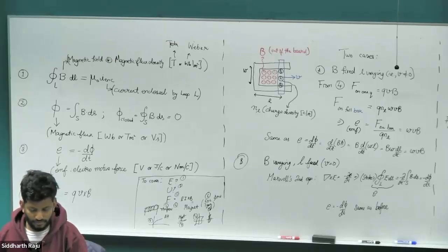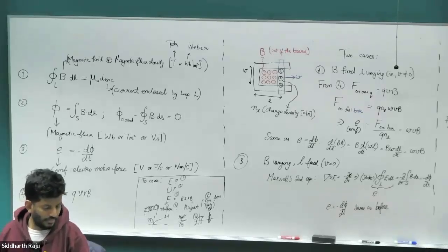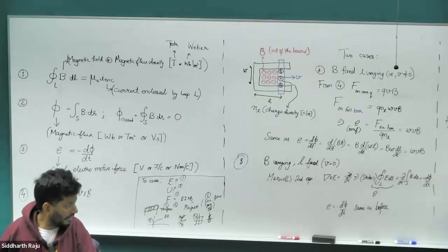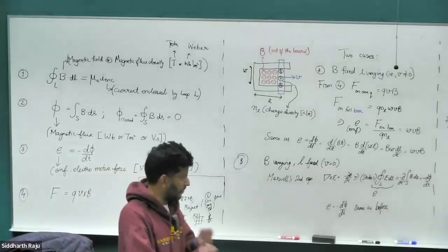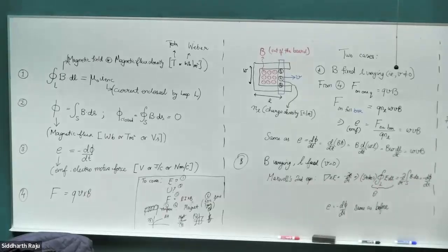So some of you, I noticed at least 6 of you, had left out or assumed the coefficient for cosines would be 0 in the Fourier series. So that was one mistake. And then a couple of you had drawn the waveforms for the third problem with switch Q1. So you all got the duty cycles for the most part correct. You got D1 equal to 0.25, D2 equal to 0.75 for the case where VO was negative 25 volts. So you put Q1 as 25%, which was absolutely correct.